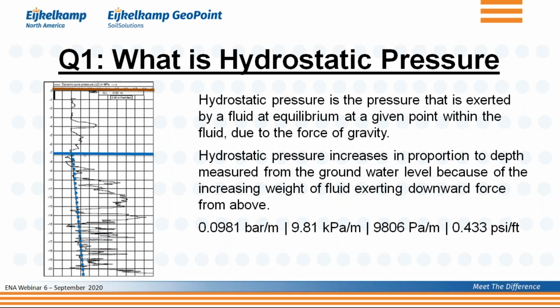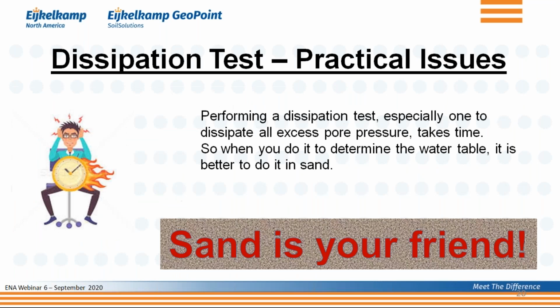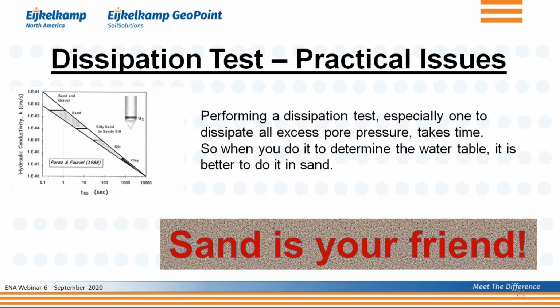Yeah, we are. Thanks for that. In some soils with high shell fragments content, we have had dynamic pore pressure in clay soil. A way for us to confirm that the cone is responding well was by performing a dissipation test. Then pore pressure would build up and start to dissipate. My question is, how valid would the dissipation test be?